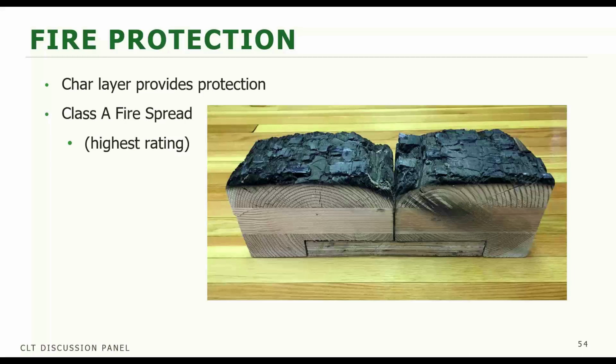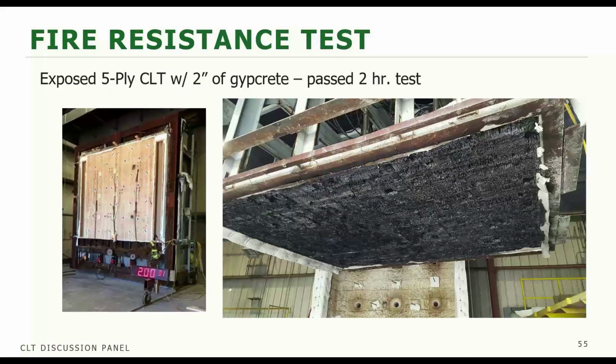So this particular panel has a Class A fire spread rating, which is the highest rating that we can achieve. And a 5-ply CLT panel with 2 inches of gypcrete can pass a 2-hour fire test. So these can be used anywhere that you need a 2-hour fire rating. And I think it's really important. There's a lot of instances where that's necessary, and the testing has been done to verify that we're getting that.